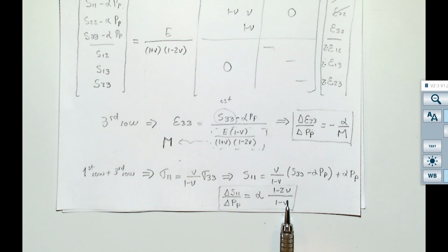What does it mean a Poisson ratio equal to 0, for example? Correct, right? So notice if this is equal to 0, then this is going to be 0, 0, and this is going to be 1. It's just going to be equal to the Biot coefficient. And that will mean that the change in total stress is just equal to the change in pore pressure.